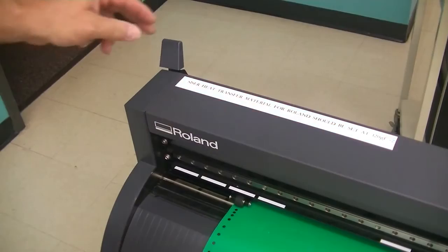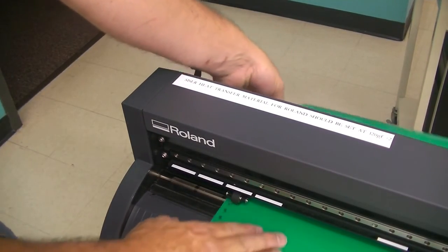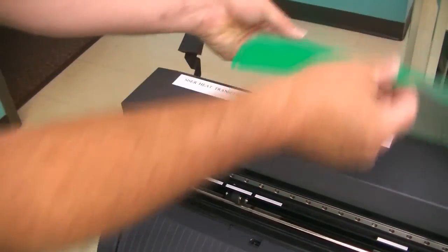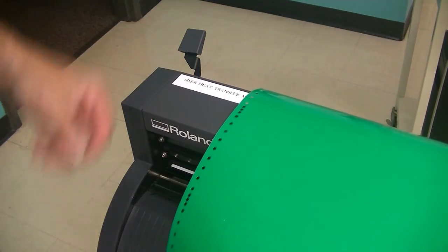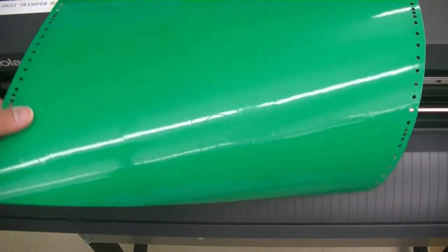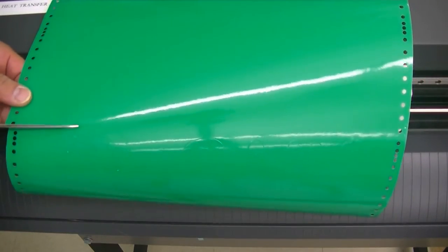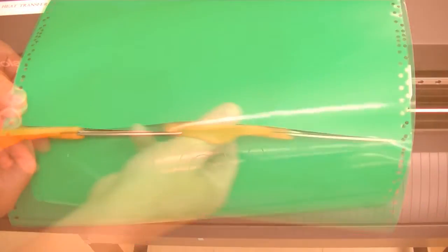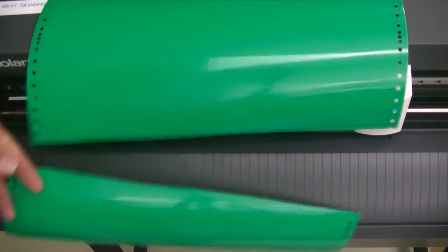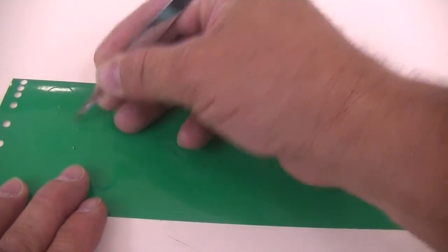After the vinyl cutter is done cutting, release the back lock handle. Pull the vinyl from the back. Carefully use a scissors or a paper cutter to cut off your pattern. Pull off the excess material you don't want to transfer.